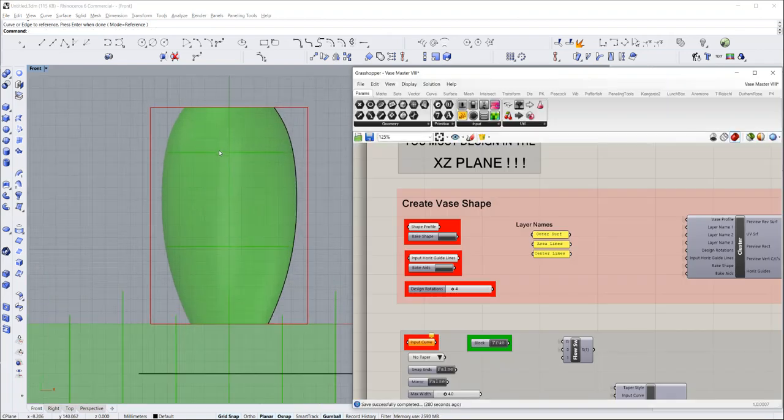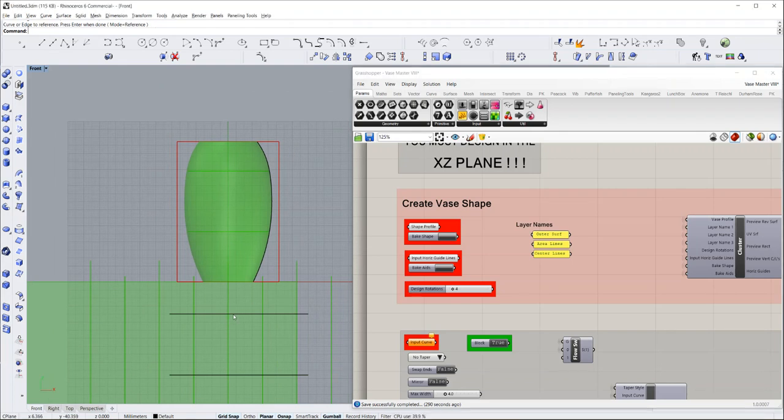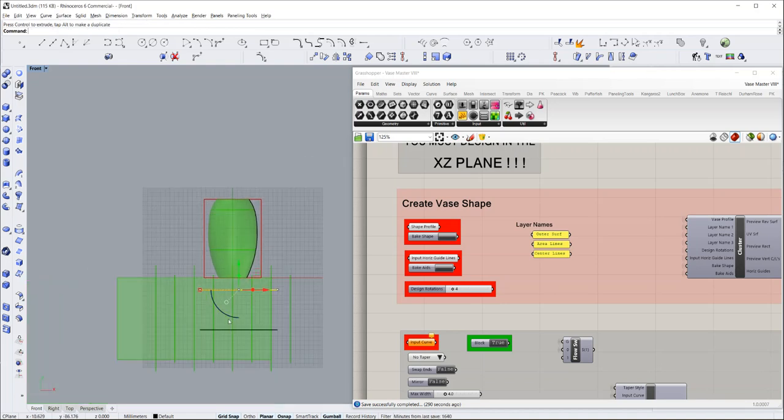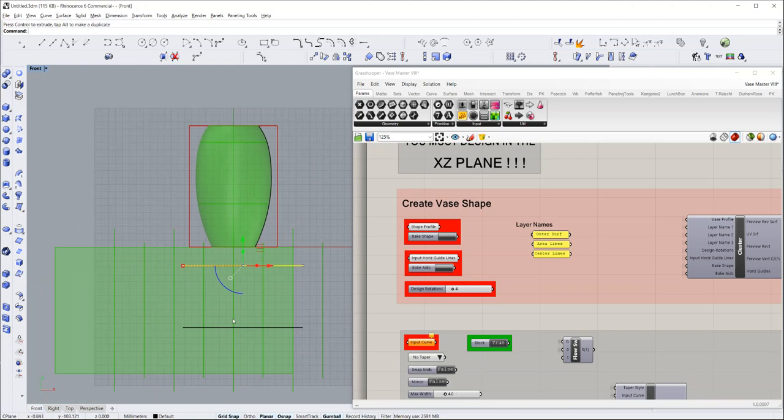And now you should be able to see on your screen a light green line appearing on our vase, and I can change where that is by moving this line. We might want to consider that to be like our canvas that we're going to draw whatever we want to design in between these 2 lines. And we'll know where it's going to appear. UV is essentially the distance along this curve is equal to this distance top to bottom. It just puts it out into a rectangular shape so you can deal with it. Okay, so we have that done.